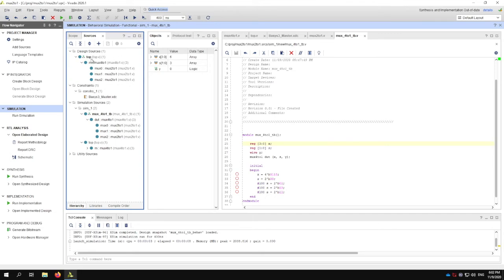One does it to map the MUX 4:1 to the board pins, and the other does it to test different values of inputs and view them in the waveform window. Finally, here's my device under test, the module that I'm testing, which is the 4:1 MUX, and it instantiates 3 2:1 MUXes. I have the whole hierarchy here. And in fact, this is never used in simulation.